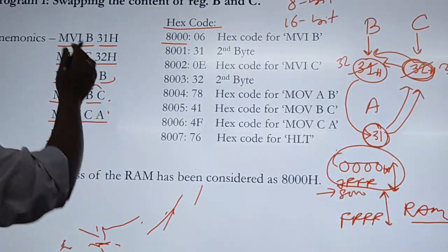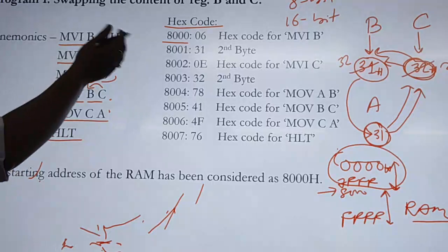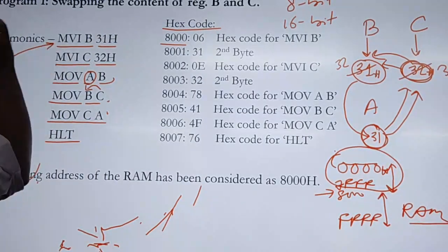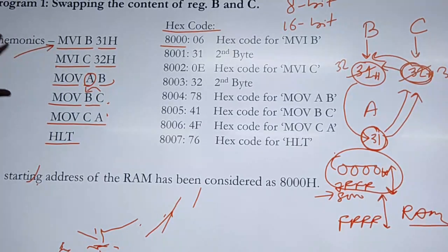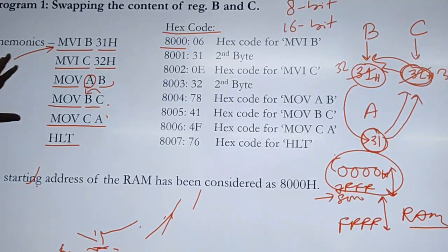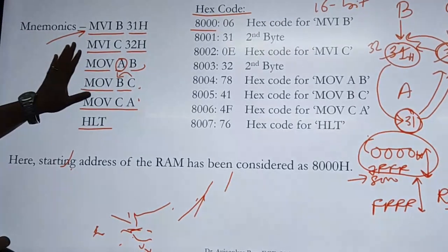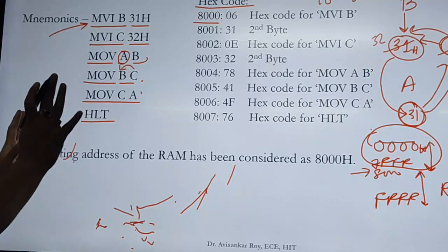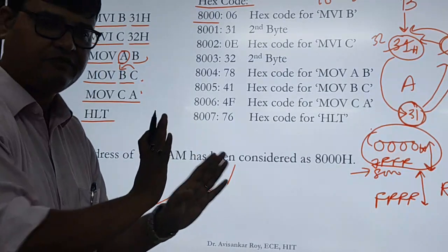So how do we convert the program into hexadecimal code? It is also very simple. First, go to each instruction individually, and find out whether there is data or an address in the particular instruction. If there is data or an address, for the rest of the part one opcode has been assigned, and we have to find the opcode from the chart. Very simple.